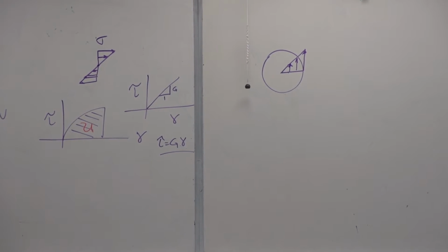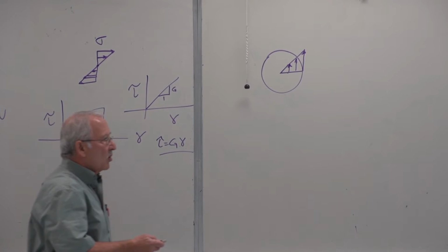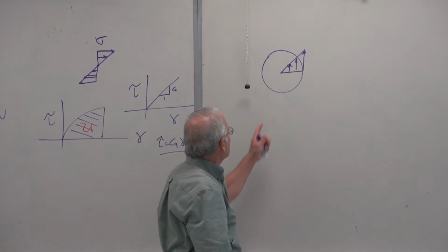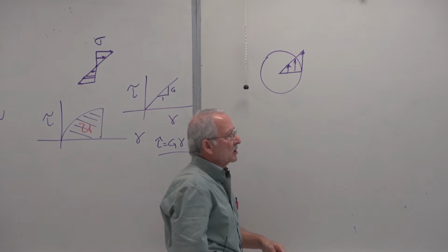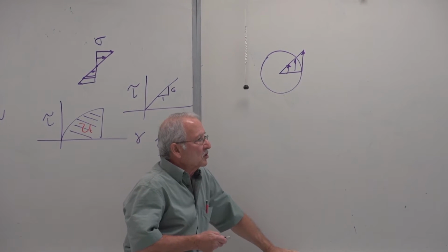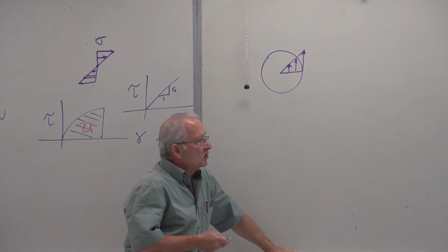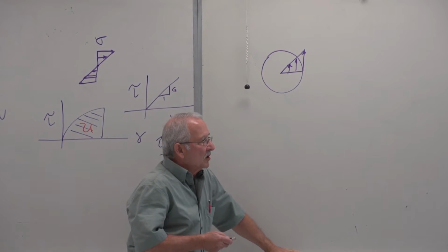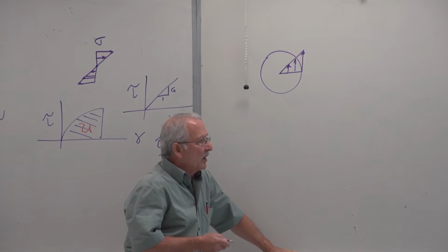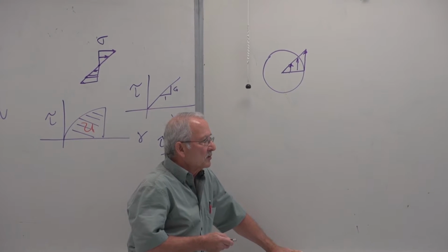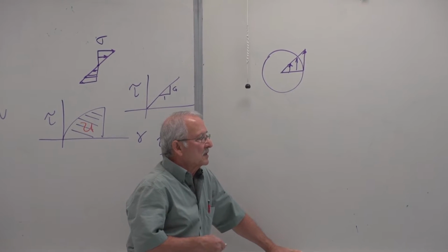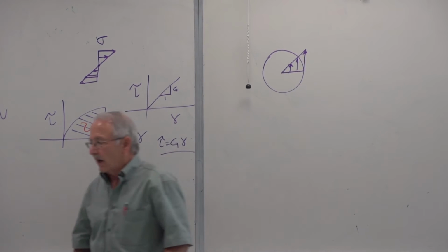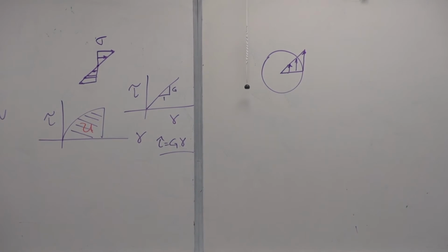It is a variable, therefore we put in T rho over J. Rho is the radius to the point of interest where you want to calculate the shear stress. So we substitute that, and once again, the integral of rho squared dA will give you the polar moment of inertia. We substitute J for that, and it cancels out one of these J's, and you get this last integral.